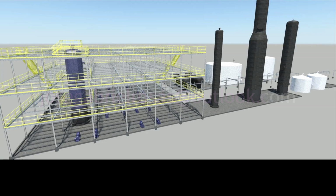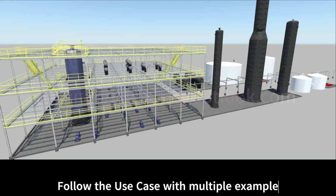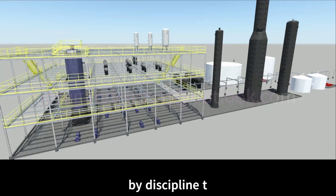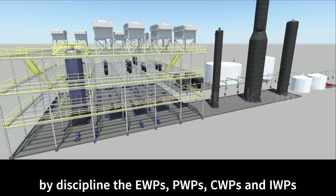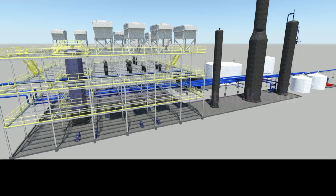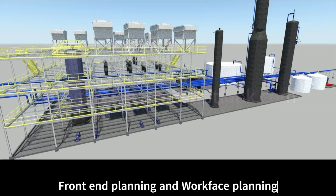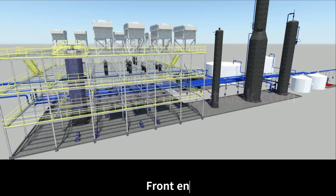With a use case, follow step-by-step how to define and visualize by discipline the EWPs, PWPs, and CWPs. Following the use case, identify different scenarios on how to define the IWPs and visualize them in the 3D model. Check the sections on front-end planning and work phase planning, including the 6 weeks look ahead, weekly work planning, and earned value management. Precision planning, paving the road for successful AWP implementation.